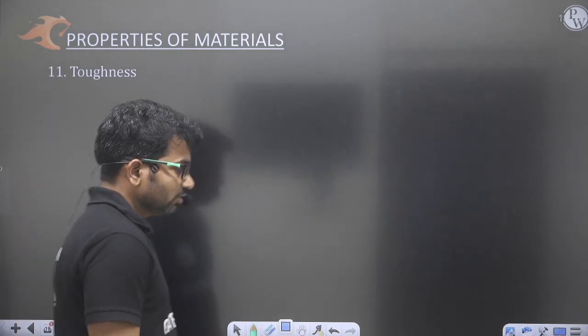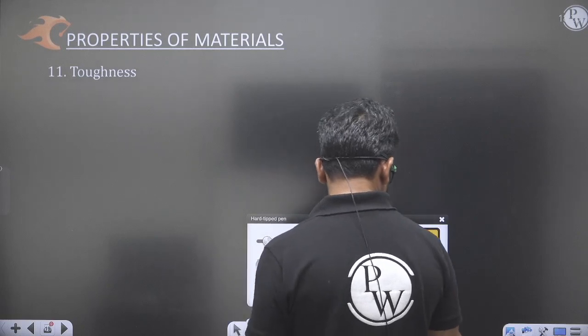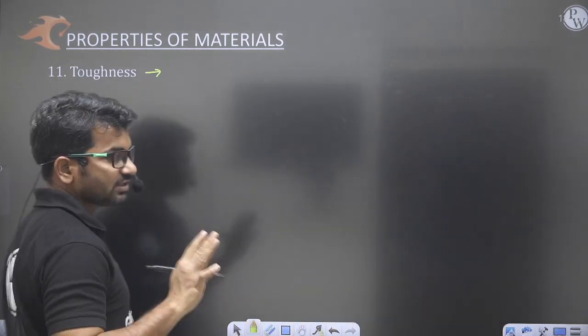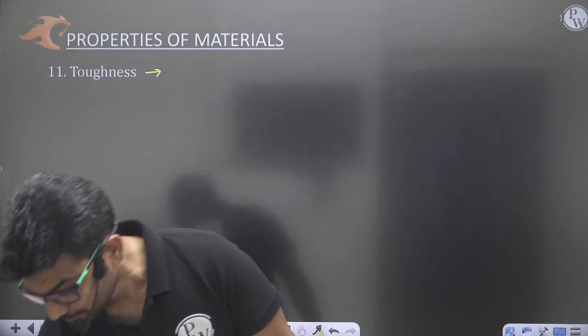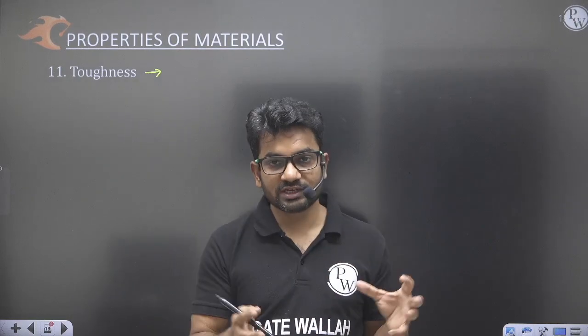Now let's move on to the next property, that is toughness. What is toughness? Toughness is again strain energy stored in the material, or strain energy stored in the total volume of the material. But resilience was up to the elastic limit only, while toughness represents the total strain energy stored in the material up to the fracture point.